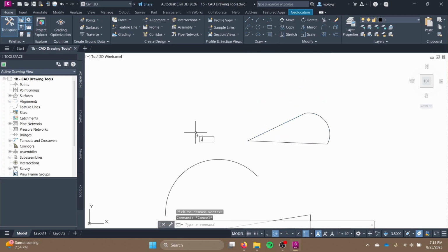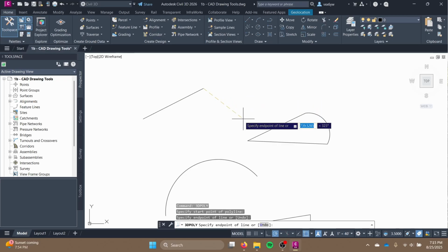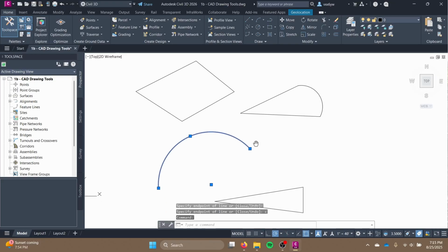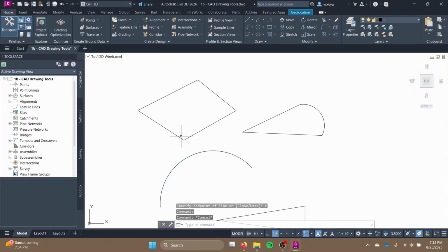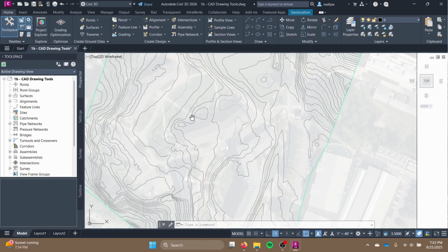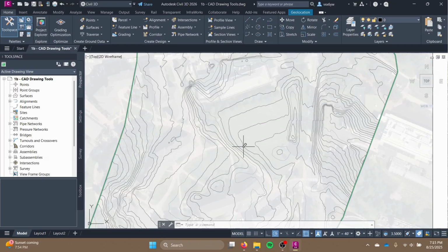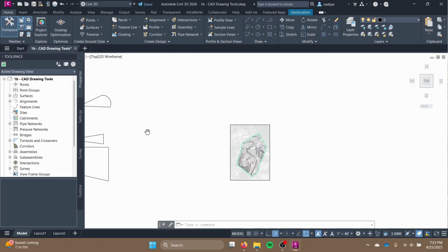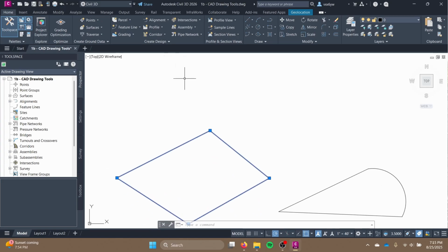Another option is the 3D polyline. You can type 3D poly for that. This functions pretty much the exact same way as a polyline, but the lines that we make all have 0 elevation. They're put at elevation equals 0. This 3D polyline does take an elevation that you can adjust as you want, or if you make that polyline on some existing surface, it will take the elevation that the surface has. So that's really helpful when you are doing your design, if you ever need that.